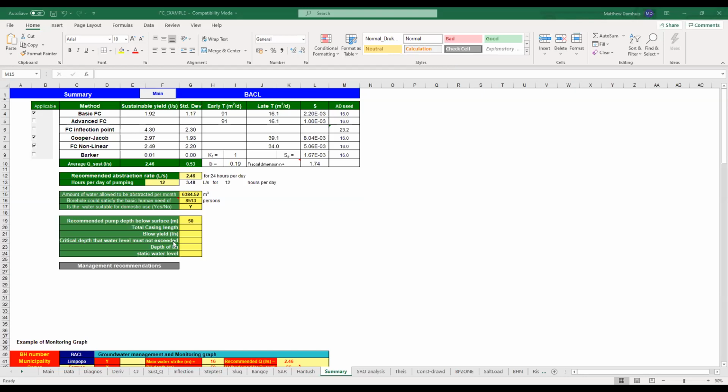Matthew, sorry, you said something about karstic environments. I didn't catch that. The sustainable yield is usually higher or lower than what? Your pumping rate. For example, if you're in a big karstic cavern, I've had it where we pumped at 86 liters a second for 5 days, and we had 0.3 meters drawdown, which recovered in 30 seconds when we switched the pump off. So the yield that we could pump that borehole at was higher than the pumping rate that we used in the test. Oh, okay.